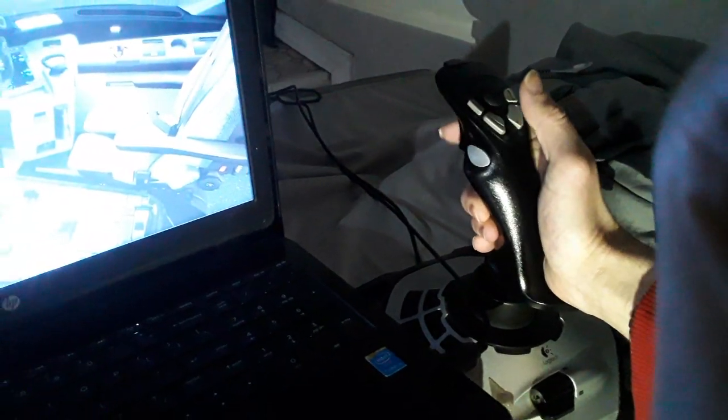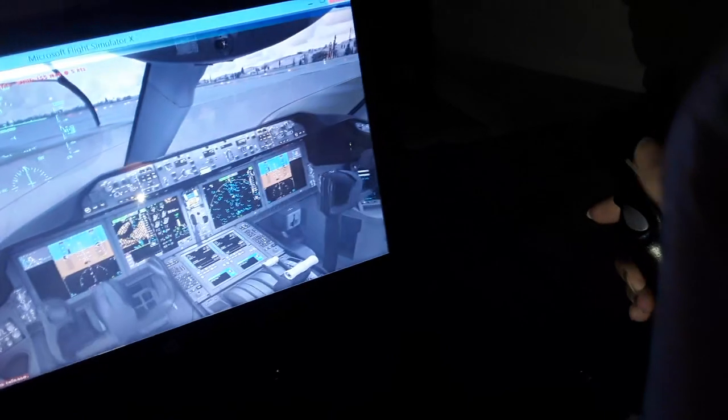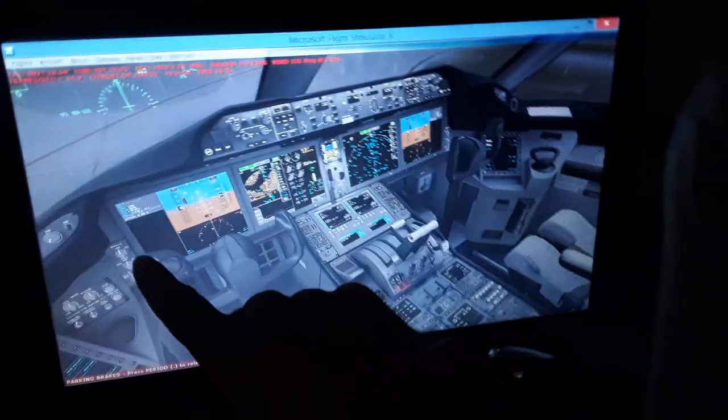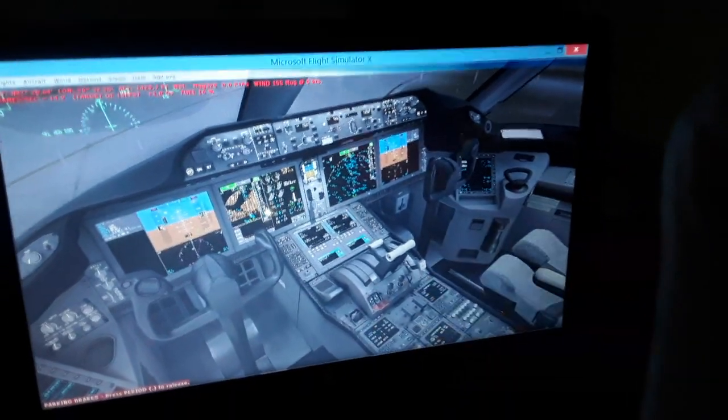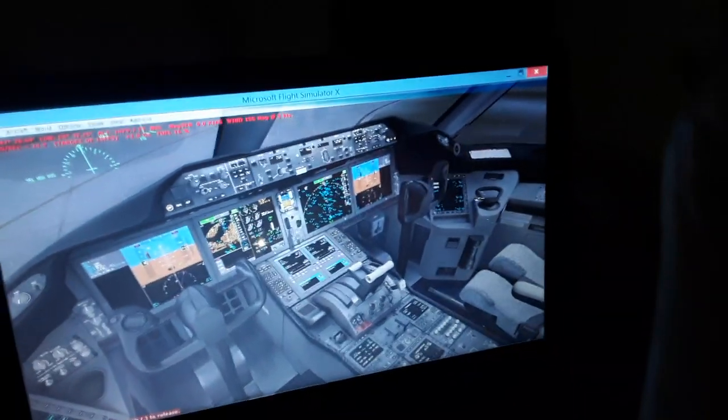So now we have the flight controls. I'm going to show you how to control the flight controls for the Boeing 787 with the side stick. You can see also we have the horizontal trim stabilizer over here. In the side stick I have the autopilot disengage for the Airbus, and the side stick priority, the push to talk button. For the Boeing we have here the horizontal tail trim stabilizer, the normal and the alternate trim switch and the cutoff switch.